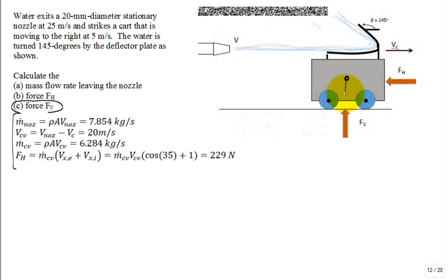Is there anything about the weight of the cart? Anything at all about the weight of the cart given in the problem statement? And so you have to assume it's a weightless cart or negligible weight. We still have this control volume that cuts like this. Instead of doing linear momentum in the x, we'll do linear momentum in the y in order to solve for F of V. But I look at this and I see that the incoming fluid is flowing only in the x direction. The outgoing fluid has some upward direction to it as well as backward direction. It's up and back. True?